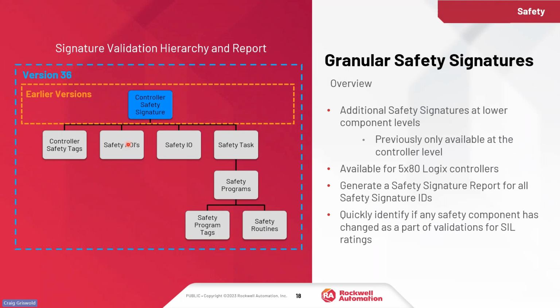Any changes made to anything in the safety, the safety tasks, safety programs, safety routines, required a whole new controller safety signature. The customer had to create a new report, and in many cases had to go back and revalidate any changes that were made in the safety environment.